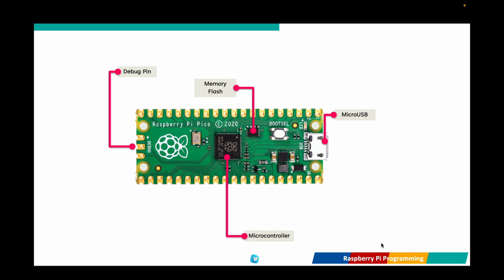The Raspberry Pi Pico features 40 GPIO pins, many of which support pulse width modulation or PWM, ADC (analog to digital conversion), and digital I/O. This includes three 12-bit ADC channels, which allow it to interface with analog sensors, something standard Raspberry Pi models lack. Unlike the Raspberry Pi 4, the Pico does not have built-in Wi-Fi, Bluetooth, or Ethernet. However, it can be connected to external modules such as ESP8266 or ESP32 for wireless communication.